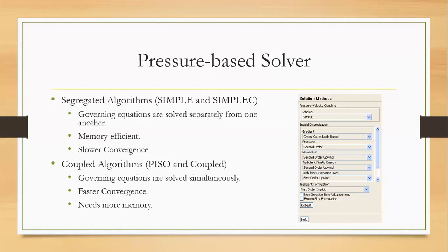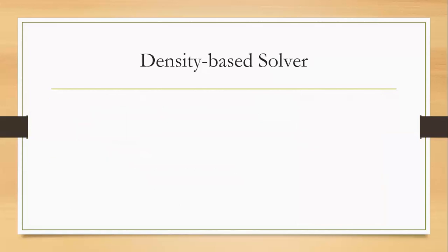Okay, so usually you have to decide, based on your problem and your computer specifications, which solver you will be using. Generally, in most of our problems we will be using only the coupled algorithm, because we are only concerned with faster convergence.